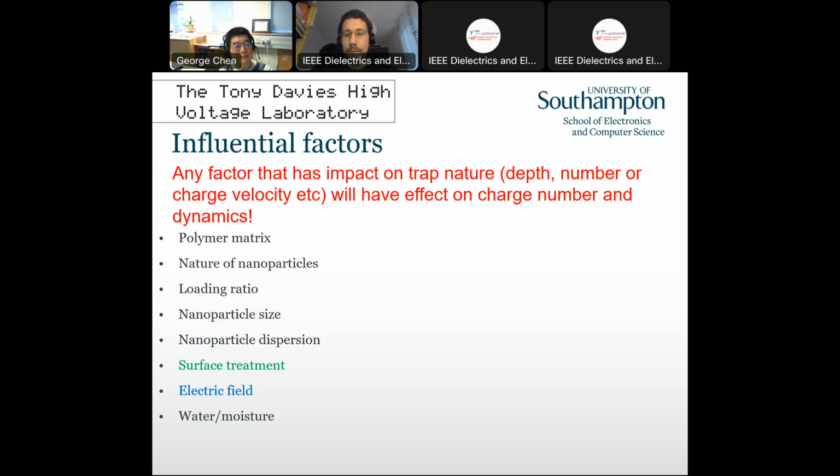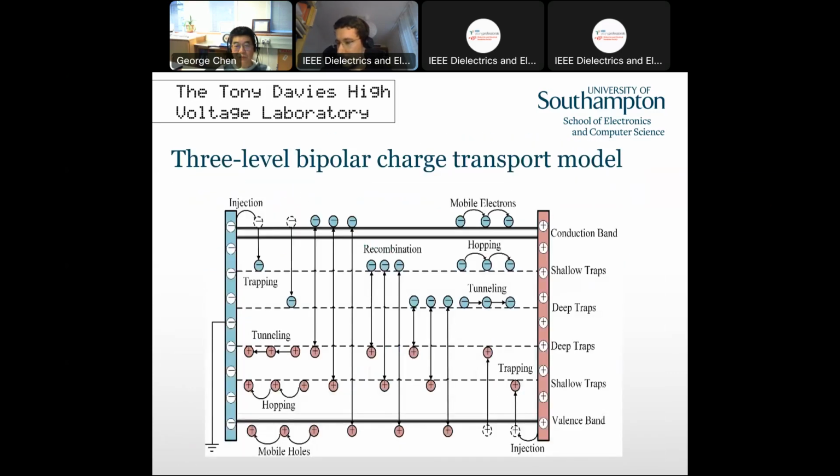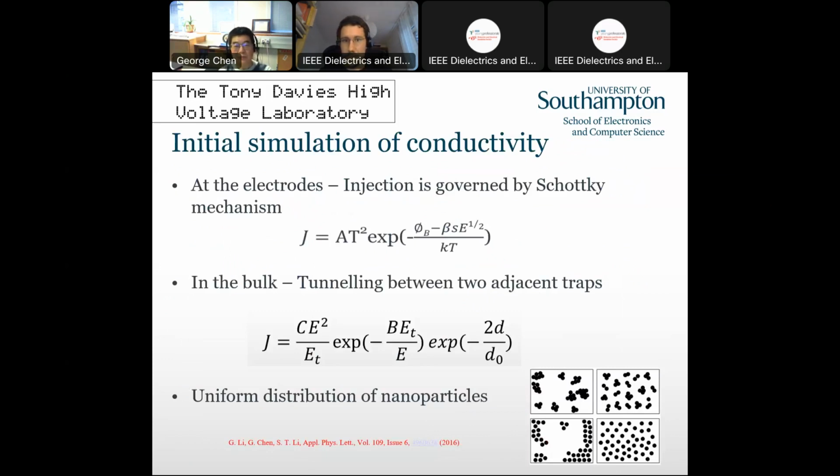Professor, I think I will have one question for you. In the last few slides, I forgot the slide number, you talked about conductivity and you said only Schottky emission and tunneling. But as you were talking about space charge characteristics in nano-dielectrics, you did not talk about space charge conduction mechanism in nano-dielectric material. So are you not considering it, or it doesn't show up somehow?